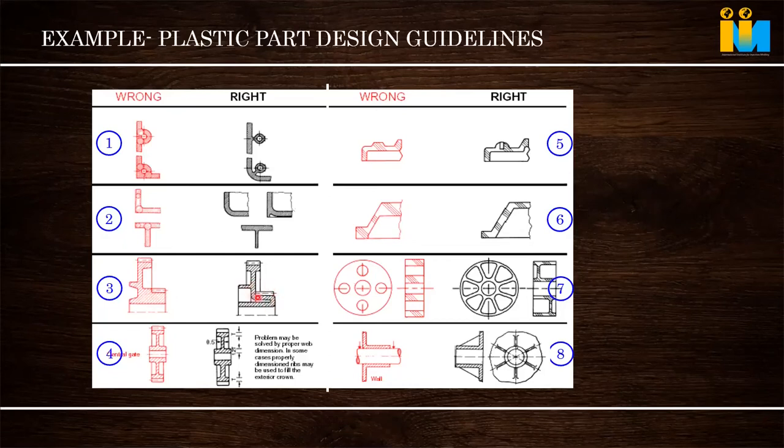So let us give some scoop-outs. Maybe a little bit of increase in the tool cost, but product cost matters. We should not see only the one-time cost. Many people think only the tool cost has to be lesser, and the part cost, what? Because somebody else is paying. See, tool cost can go up, but wherever recurring cost comes, if it is 1 paisa, we should not waste that, because in 6 months we can make a new tool with that cost. So we have to take it. Sometimes raw material scarcity will be there. You are wasting, instead of 2 gram we are using 5 gram, by putting a thicker area.